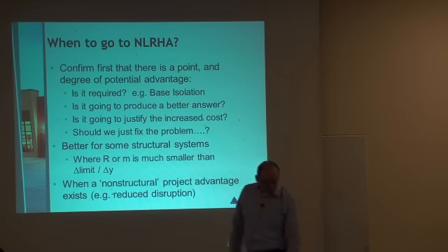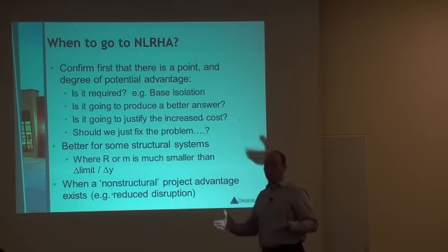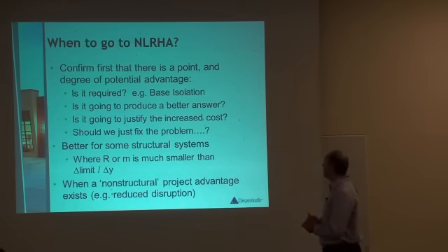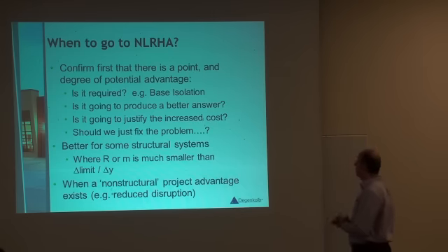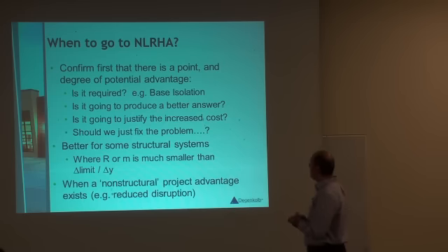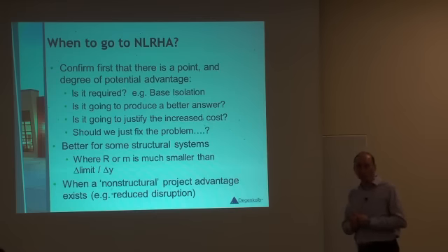Okay, so finally, let me start wrapping up. Why do nonlinear response history analysis? It's a lot of work. It's tedious. In practice, often you can design a building without having to go through that. So why do we do it? Sometimes it's required. If you have a base isolated building, you have to do it.